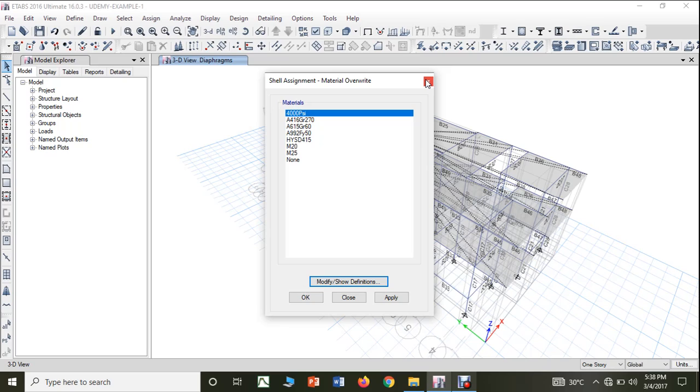So when you do that, definitely you have to give all those details. So while doing that, since you have defined the new material properties or the new method, definitely you are supposed to override that here. That means it may have some different stress strain curve, so you have to define it. Then only can it be assigned, and when you assign it, the software will assign according to that. Okay, that is how it is for the material override in case you are using any new material.